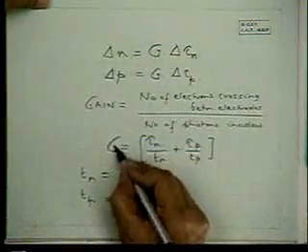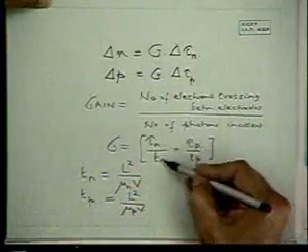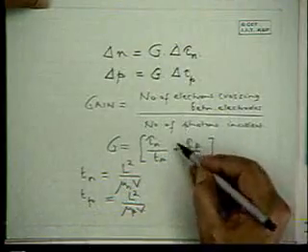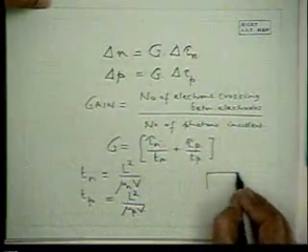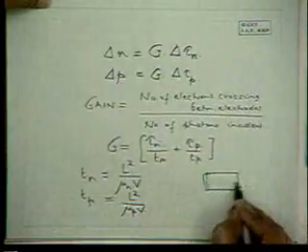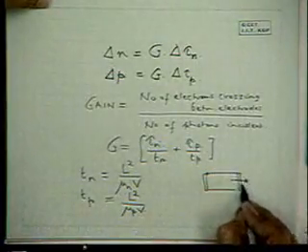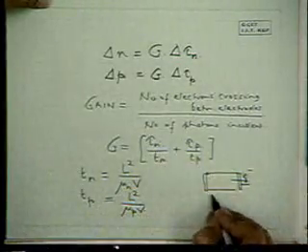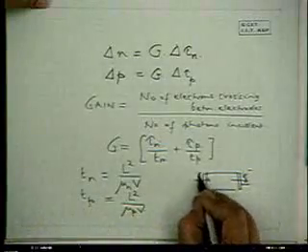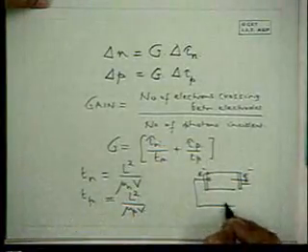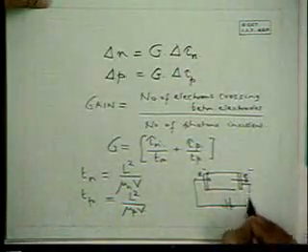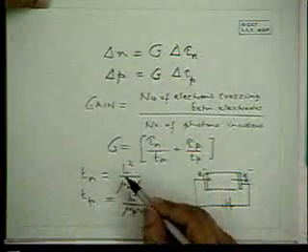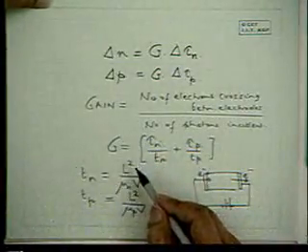Essentially here, the gain can be large if the transit times are small compared with the lifetimes. And in that case, what we are having is that if tau n is much larger than Tn, when an electron exits at an electrode, then another electron is injected, and that keeps on circulating until the recombination time is reached, and that is the reason why gain is possible in a photoconductor.